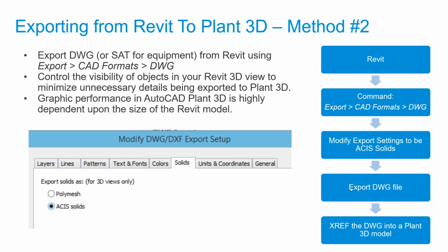What you can also do in Revit is create portions of the full Revit model as DWG. What we sometimes see is customers getting too big exports from Revit. Of course, it makes more sense to split it, for example by floors if it's a building. You can do that by creating 3D views in Revit and then exporting from these views.